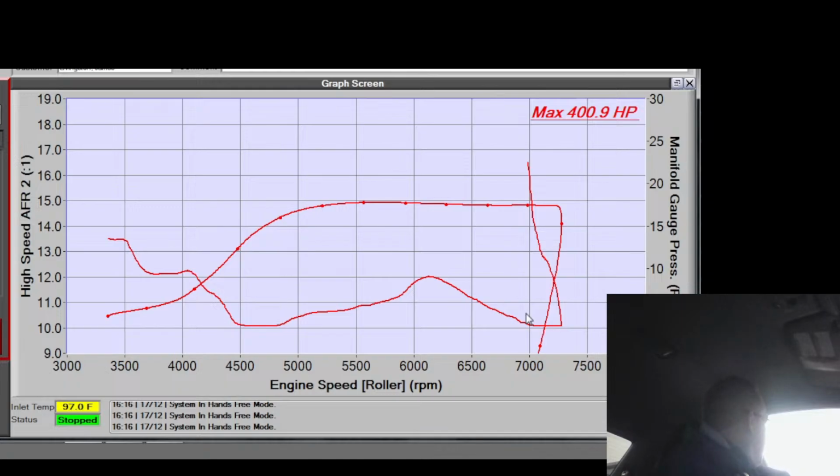Yeah, and it comes on super hard too. It's not even that. It's late and hard. It's late. Whereas the other one's softer as it comes in. And then the fuel's everywhere. I mean, it might help a little bit not having so much richness right there. Another thing too, this has the ETS style downpipe too. So tight 90. Pinched off the back of the turbo. Yeah, that was the exact reason why I said I want the turbo down low.